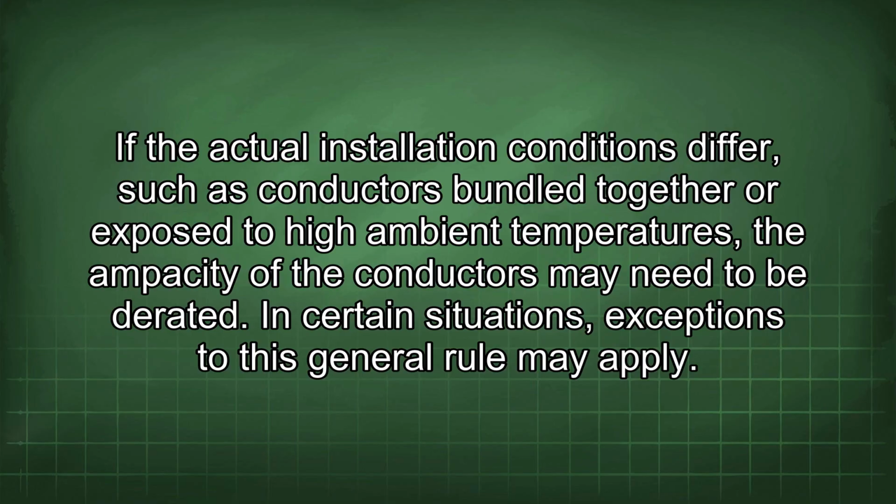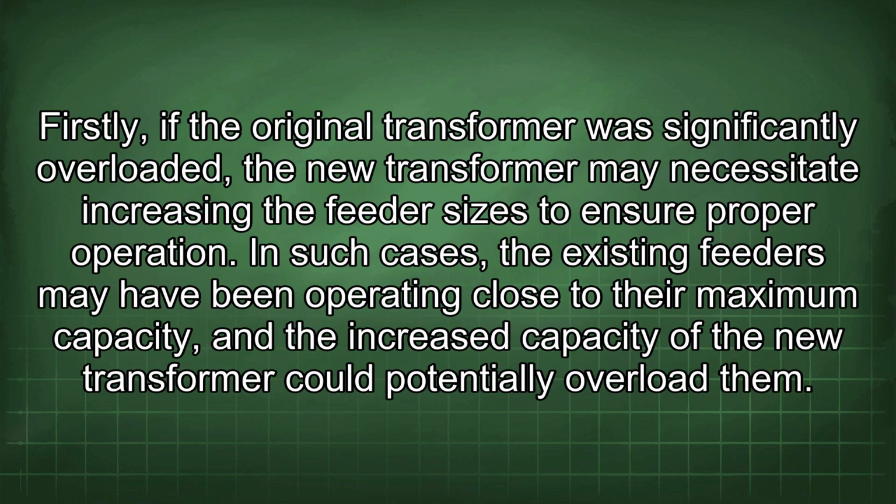In certain situations, exceptions to this general rule may apply. Firstly, if the original transformer was significantly overloaded, the new transformer may necessitate increasing the feeder sizes to ensure proper operation. In such cases, the existing feeders may have been operating close to their maximum capacity, and the increased capacity of the new transformer could potentially overload them.